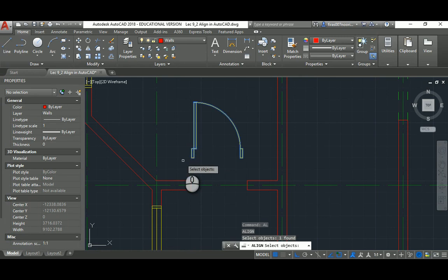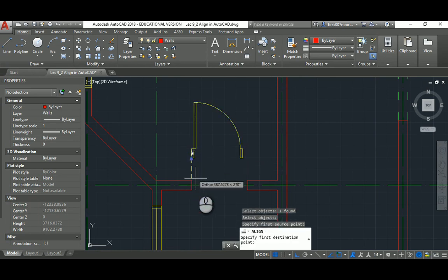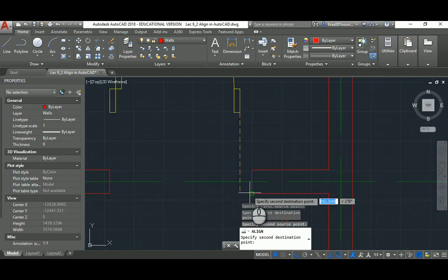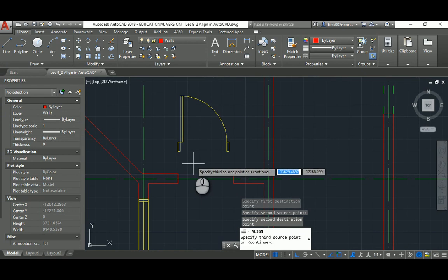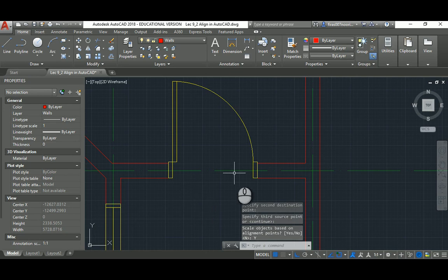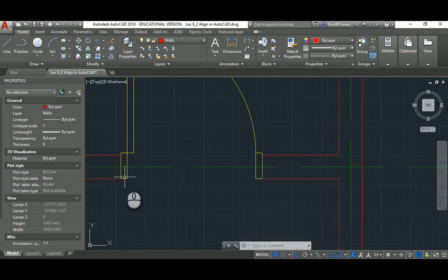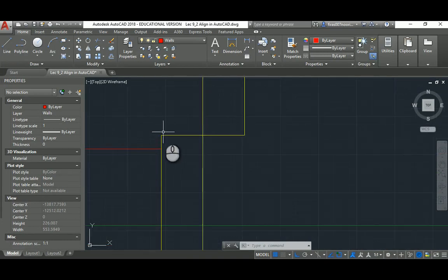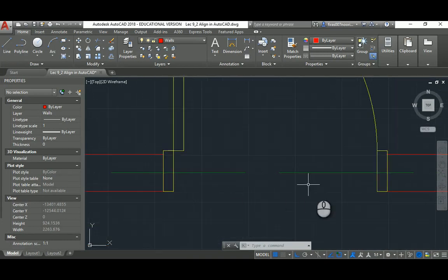So I select the object and hit space. Now you see it goes with this point to this point, and then this point here to this point. Now that's the important way. Hit space and yes. You see it fixed this issue and immediately changed the width of the object, but it created an extra distortion: it increased the X, and it caused the Y also to be stretched and increased.